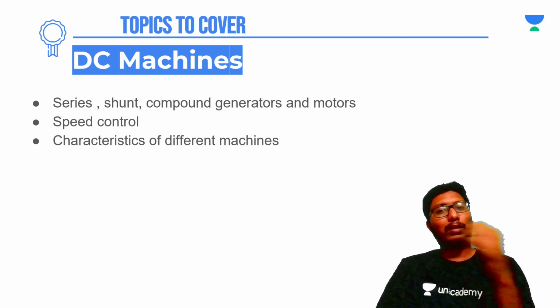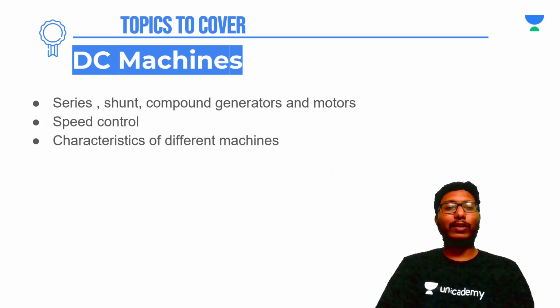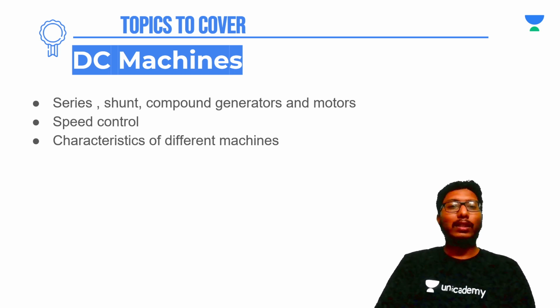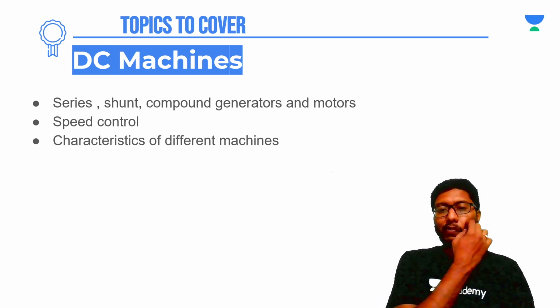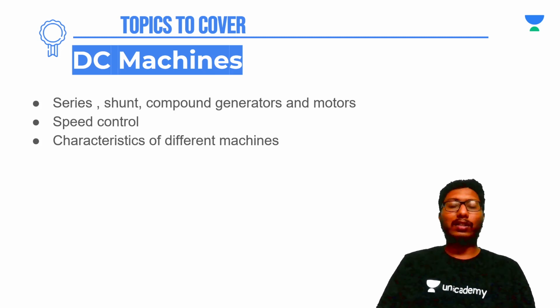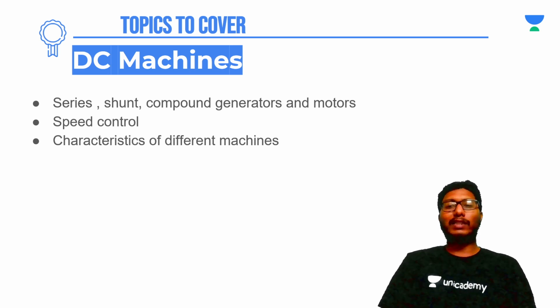Starting from the basics of DC machines, we look at magnetic circuits, construction, and different types of machines. These are not that important. If you don't know much about the basics, that is fine. You can start from the EMF equation and the equivalent circuit of a DC machine, and you can start solving problems. The basic EMF equation you should know is phi P Z N by 60A.